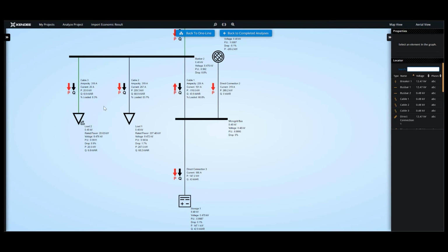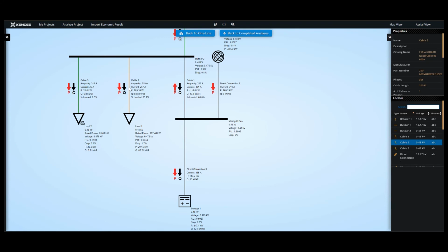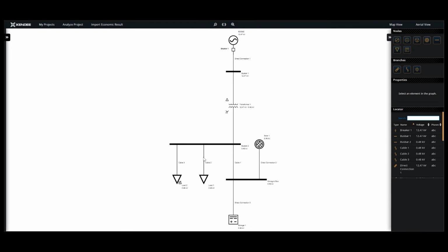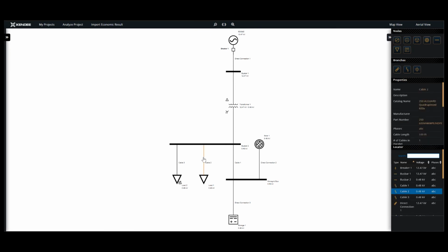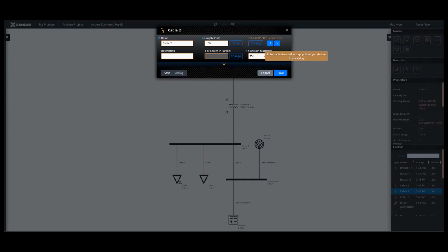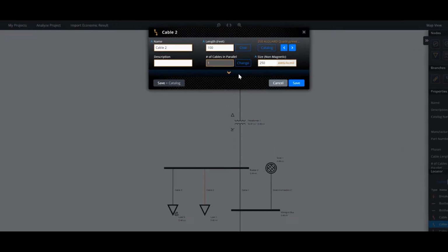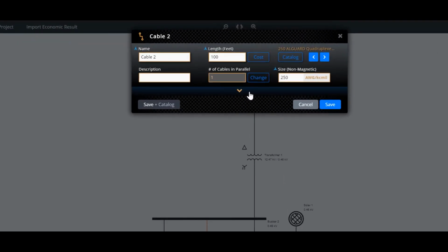But when we look at some of this, also, even though something is normally colored, you might want to be thinking future as far as from a planning perspective. So this cable here, it's fairly loaded, which means if we do anything more or we want to add additional loads inside of our building, we might not be able to do that. So we have a few options here on how we can do this and look at the impact of it. One is you can just put in a bigger size cable. And there's some advantages, some disadvantages.